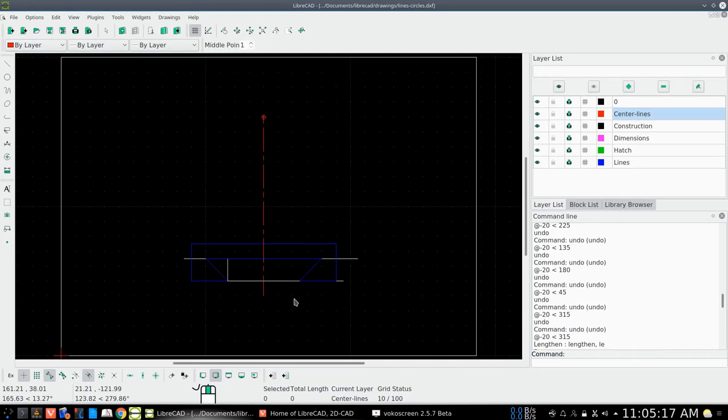Now what we'd like to do is we have a unit going 70 units on here, and find the center of that will be 35 units up. So what we'd like to do is go back to the construction line here. Let's turn this one off for a moment. Let's go to the construction line, and we'll also find middle. Okay, with a line here, let's add a line tool.